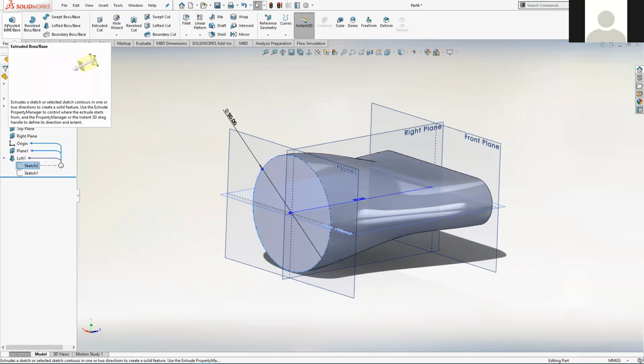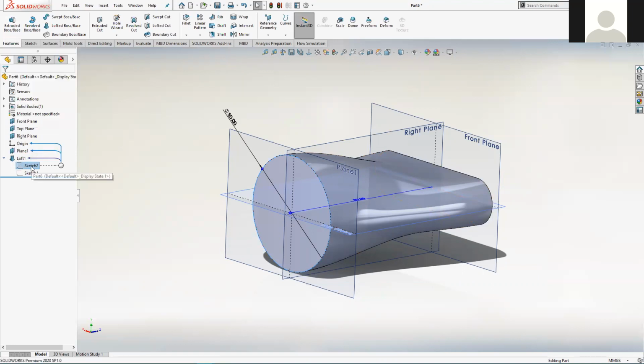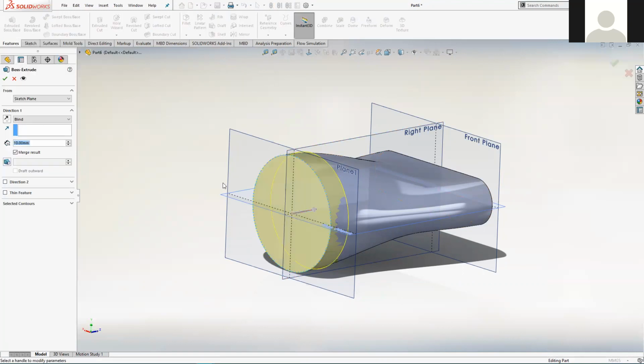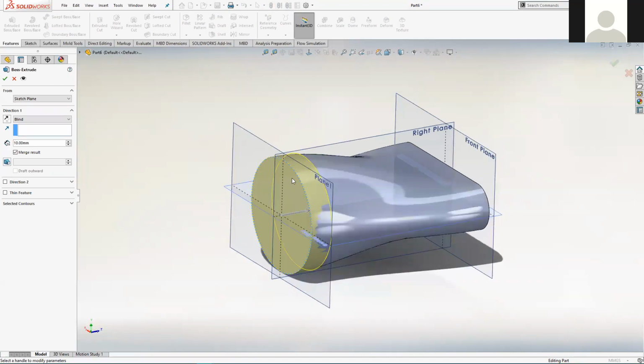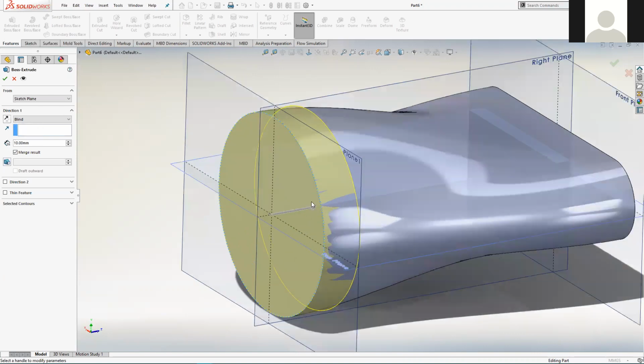Then we can say to the system, I've pre-selected a sketch, I want to create an extrude using it, and it does that. So rather than us having to create a new circular sketch, which is extra work, but it's a sketch that could possibly end up the wrong size. If someone came in and changed the loft shape, the circular sketch that we may have created after that may not be linked to it in terms of its diameter. So it's easier to do it this way. It's picked the wrong direction, so I'll flip the direction.